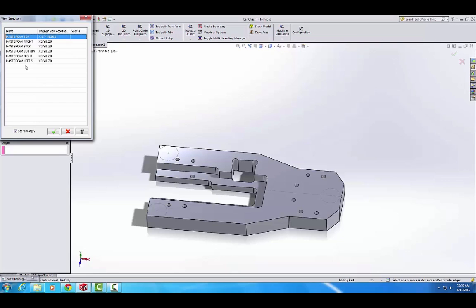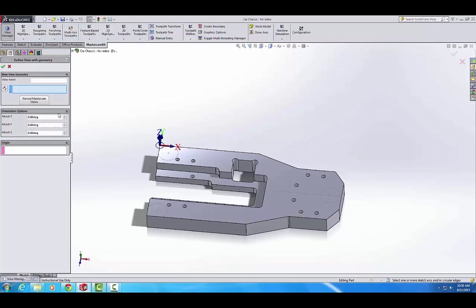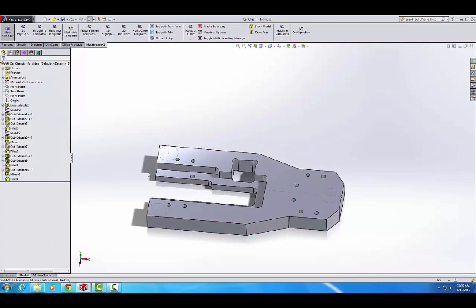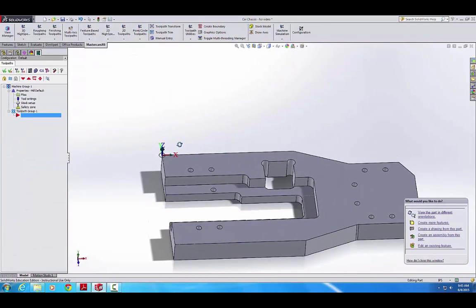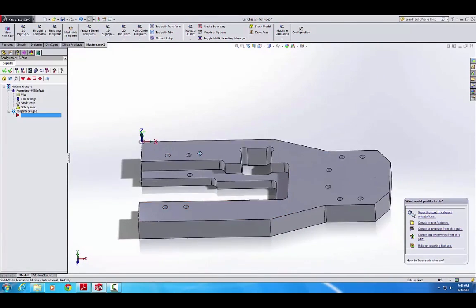So you choose whichever view seems to match the best, click OK, and in our case, let's say the origin was rotated the wrong direction. You can use these text boxes to rotate the origin into the correct position within your custom view. In our case, we don't need to do this, but this is just a quick note. Now, the origin is where we want it to be.